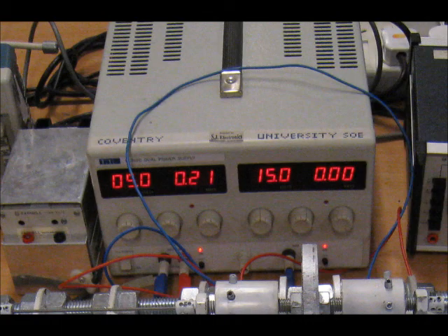The experimental setup has to work with a laboratory voltage source which provides up to 30 volts and 2 amps. The motor has a resistance of 1.6 ohm, which leads to the problem that the maximum current is exceeded easily when the controller calculates a high duty cycle of the PWM signal. This leads to system failure with a high chance. To avoid this problem, a maximum duty cycle which is dependent on the speed of the motor is calculated.